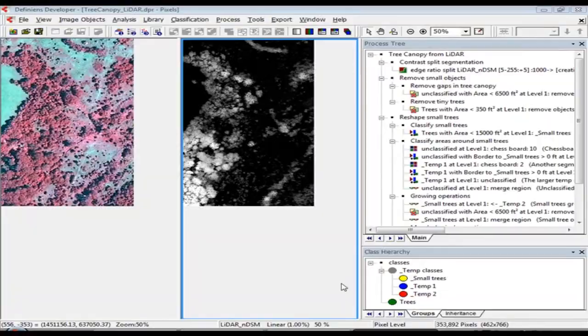than the aerial imagery. The LiDAR data is a normalized DSM or normalized digital surface model. In a normalized digital surface model, each pixel represents the relative height of features. So that is, the LiDAR data has been corrected relative to the bare earth terrain.